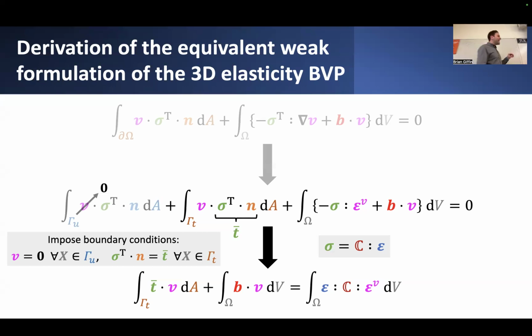And we've directly included things like the external traction boundary conditions within this expression. So rather than tacking on additional requirements that we also have to satisfy these traction boundary conditions, we've said, take all those traction boundary conditions and plug them directly into this statement of equilibrium so that now they're all nice and consolidated.